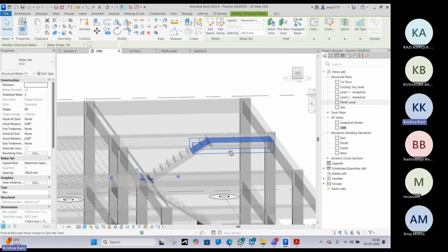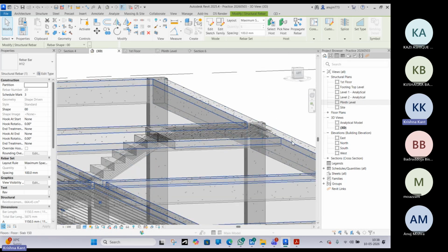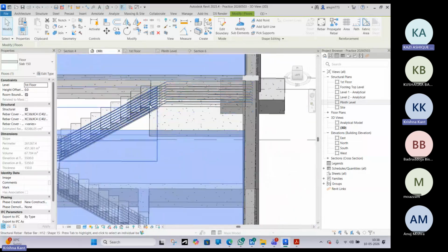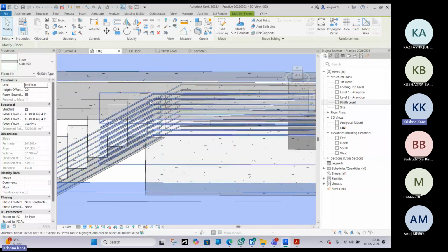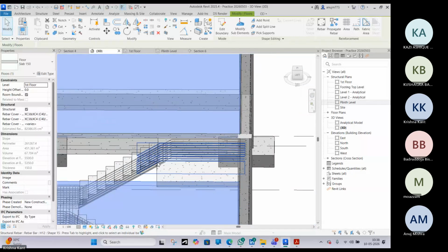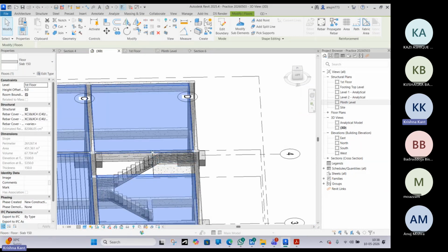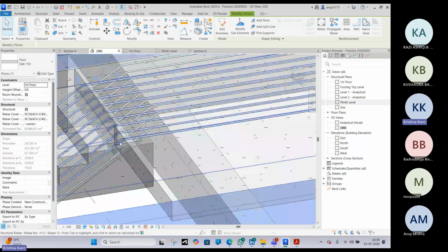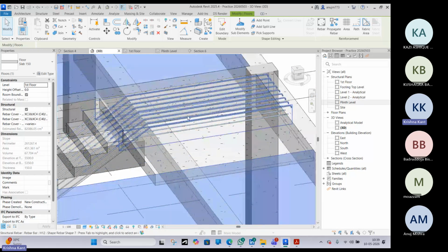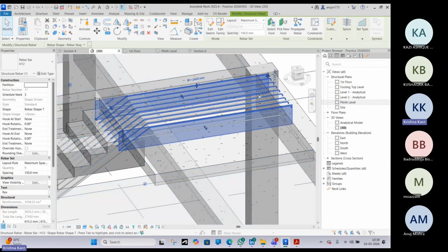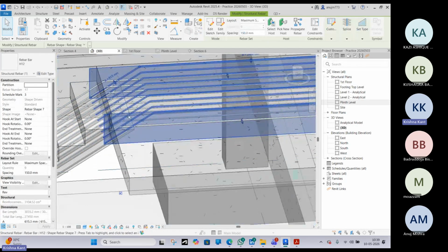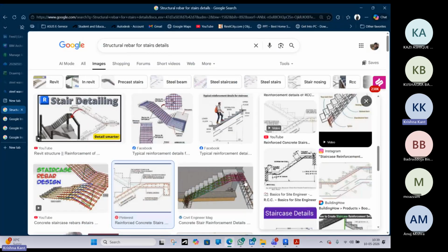Also, sometimes, as I have given an example, the beam is over this end, right? In some of the projects I have seen, the beam will also be in this portion, similar to the bottom. So that beam will carry all the load over here. So no need to terminate the top landing rebar till this end. What will happen in that scenario? All the rebar will be terminated in the beam portion only.